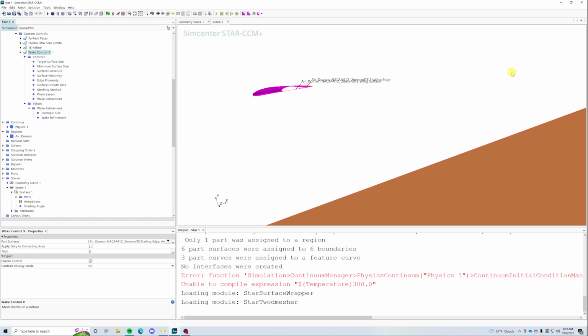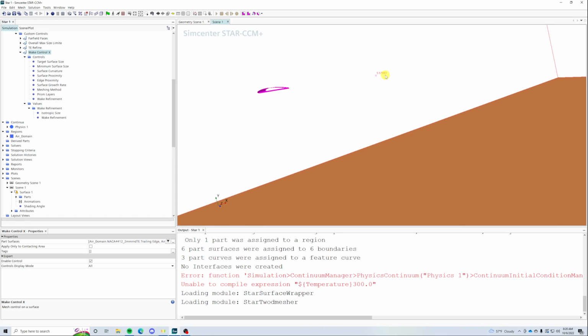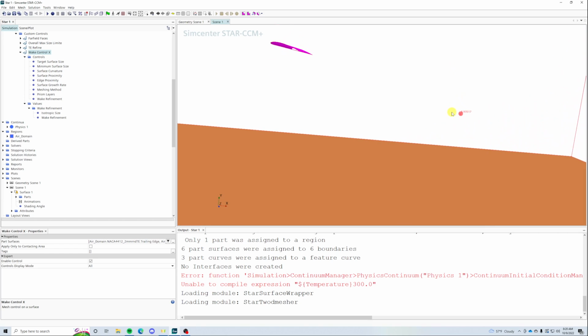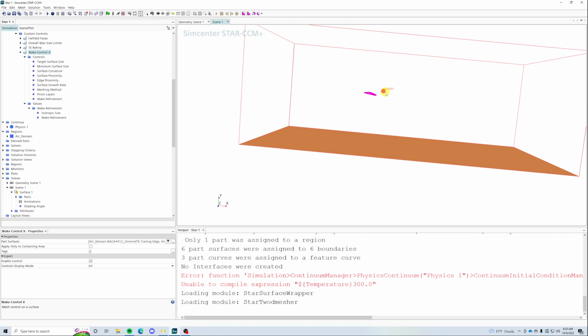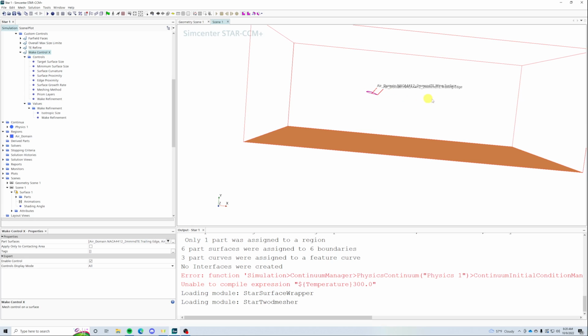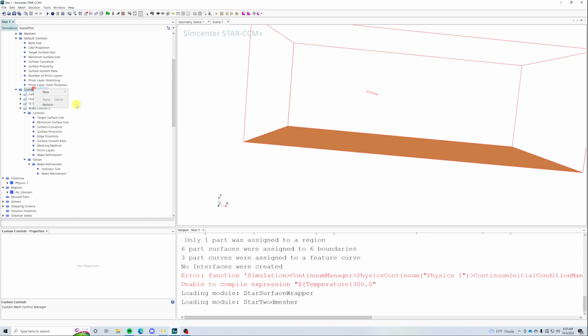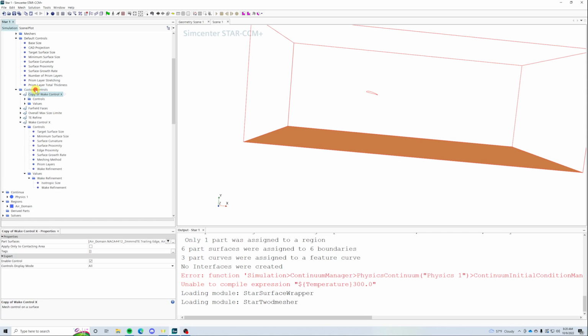But this airfoil is going to rotate, right? At some points, it's going to be at quite a high angle of attack. Airfoils at high angle of attack don't just have flow go backwards, they have flow go down. We'll very rapidly leave that cone. We're going to create a new wake control. I'm going to call this wake AOA.